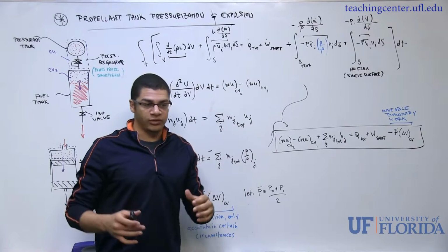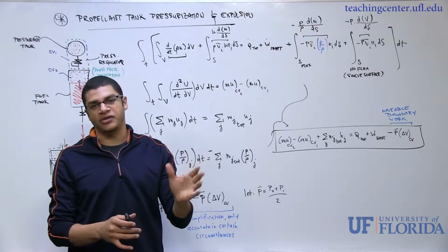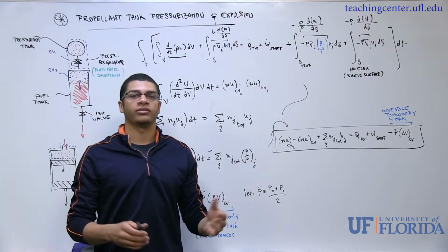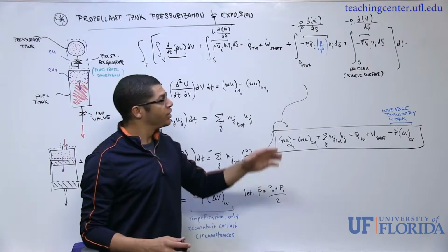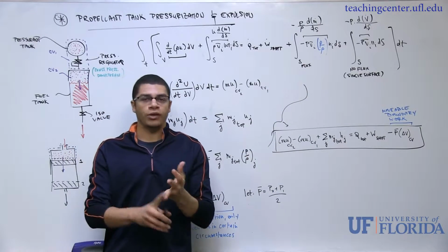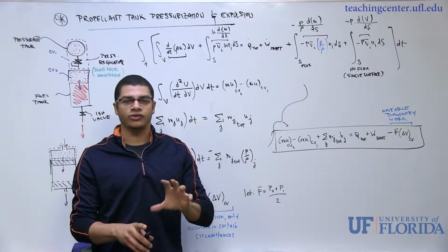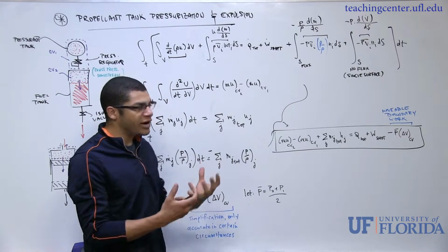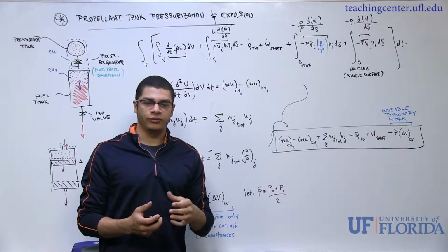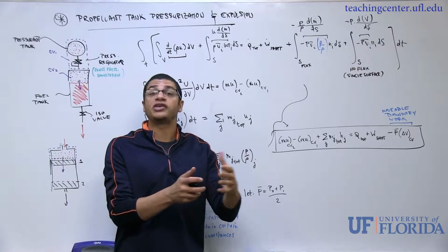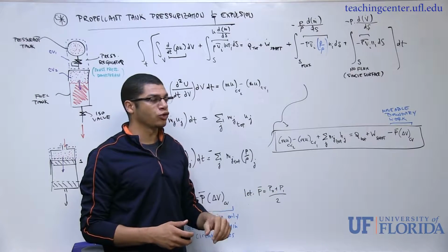It itself and all the upstream fluid is acting as a piston in order to push fluid into the control volume, and vice versa if we were considering an outflow. So this is what we call boundary work, or pressure work, or flow work. There are a number of different ways that we can describe it, but it is the energy required by a fluid to displace adjacent fluid when it's moving into our control volume.